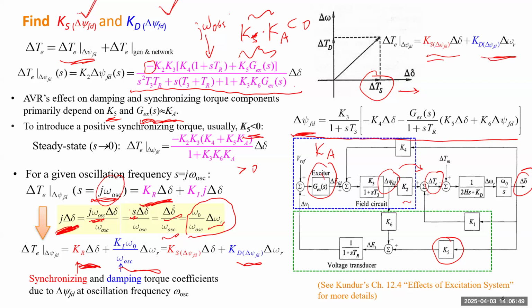I have a paper from a few years ago. I followed exactly the same approach to study the cause of the sub-synchronous oscillation caused by a wind farm. Even though that's not for a synchronous generator, it follows exactly the same idea, because for the wind farm the oscillation can be caused by some component. You design a transfer function similar to that one. For a generator, that transfer function is from the angle deviation to the electric torque, electric power. But for a wind farm, you can have such a transfer function maybe from voltage, current to something else.